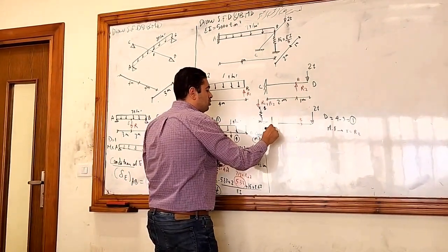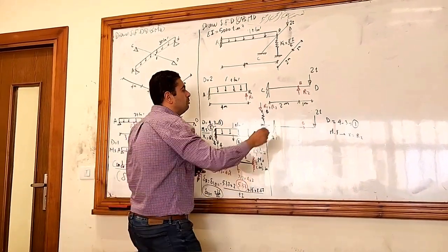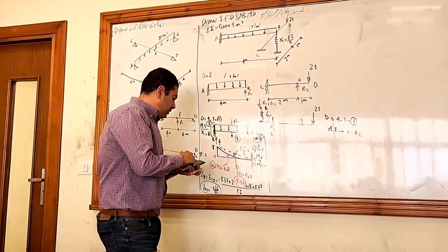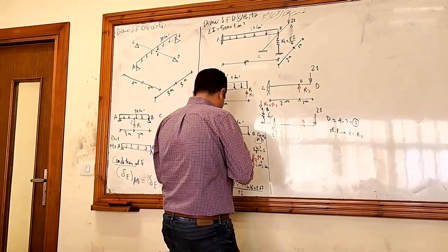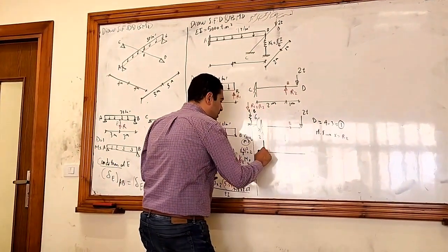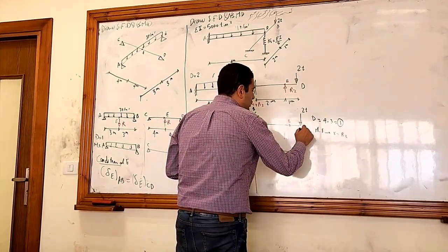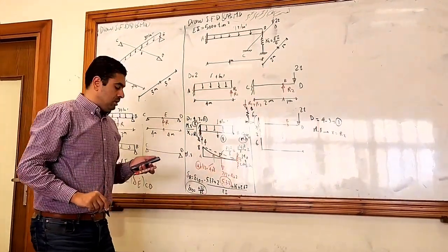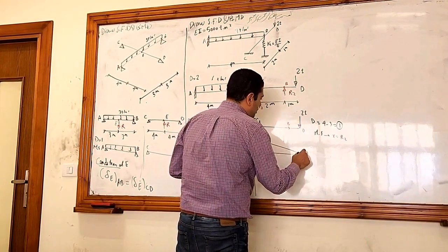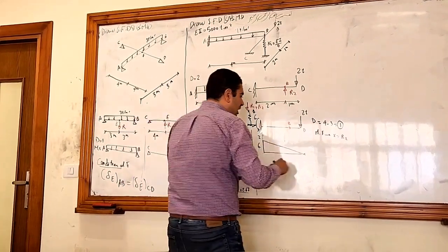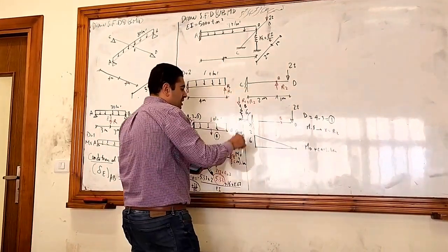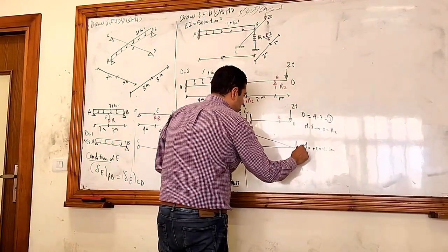Let's calculate the reactions to draw the bending moment diagram. Only I have 2 tons, so the Y here will be 2, and the bending moment will be 2 times 3, 6, right? Let's do the bending moment diagram. Take care when drawing the bending moment diagram. Here the moment is 6. Here the moment at D is 0, right? And then straight line, knowing from distributed load, so straight line. Put it on the conjugate beam, so this is called M node, plus conjugate beam. The conjugate beam here fixed will be free, and the free will be fixed.